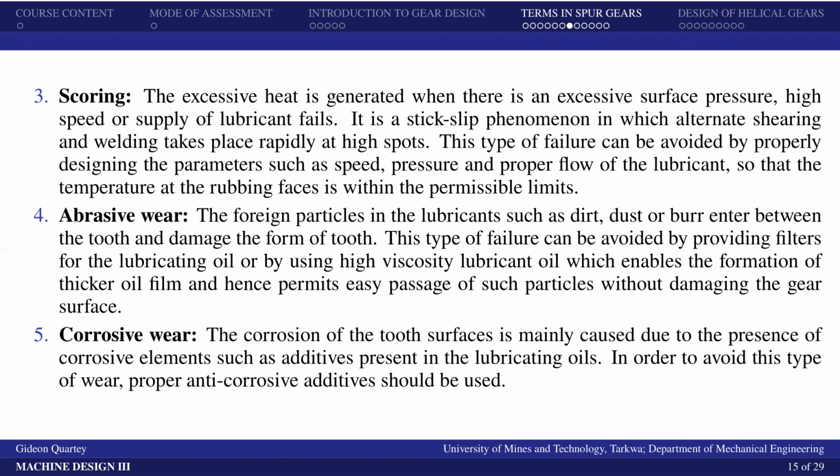All right, so when the teeth are in contact, we know that there is high pressure at the surface of the gear teeth. So as one moves on top of the other, that high pressure may create some welding at the points of contact because of the high heat and pressure that will be generated.